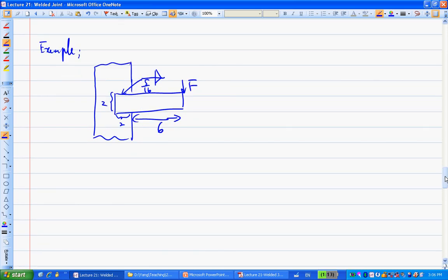Right? Yeah. So if I calculate the stress of critical location, first of all you got to basically look at what does the weld group look like? What's the geometry of the weld group? Right? So basically, where do you get the information from? This symbol here. The weld group meaning you have portion at here and portion at here, right? Okay, yeah.